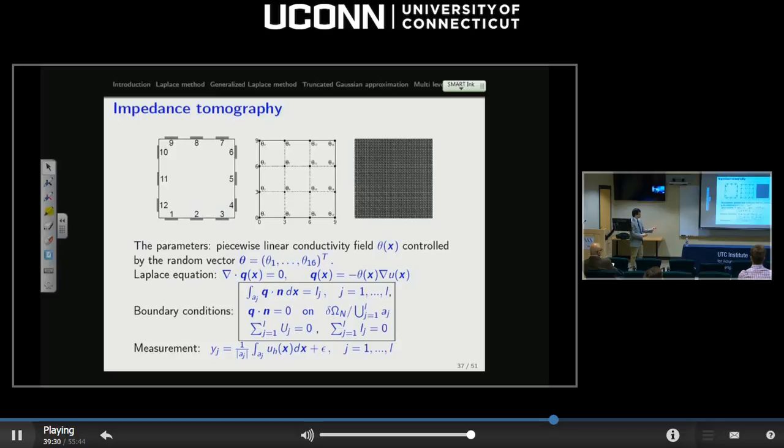We can specify the density of the electricity, and anywhere else on the boundary it is a traction-free boundary condition. Also here we need to define the reference of the electric field, otherwise it will be ill-posed. The measurement is the integration of the potential at the selected electrodes.